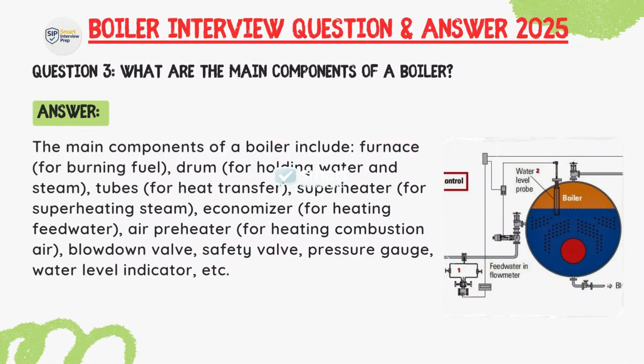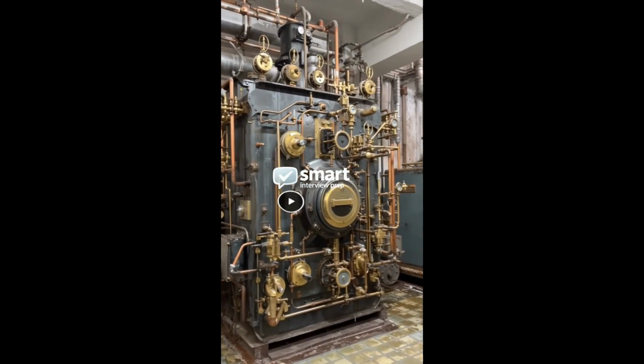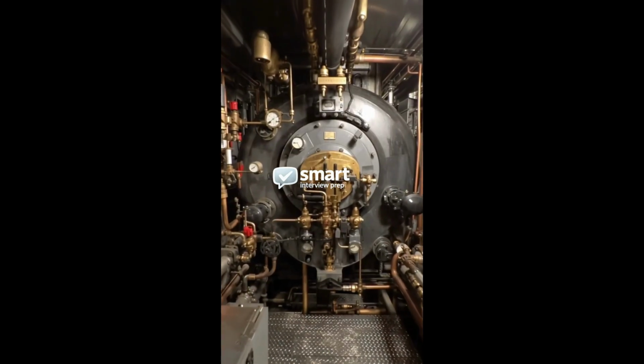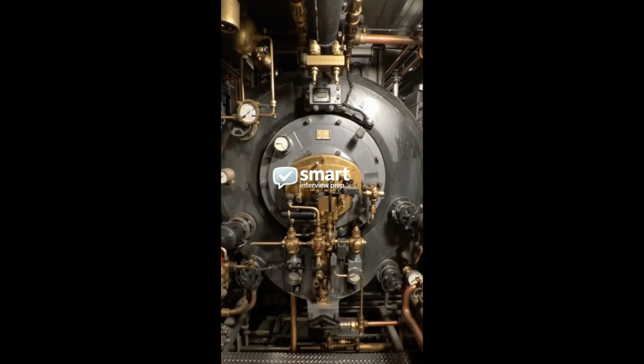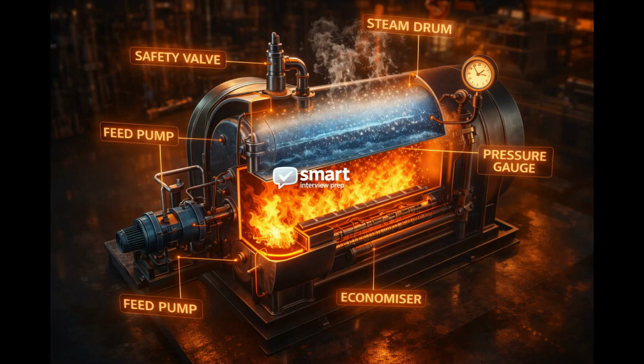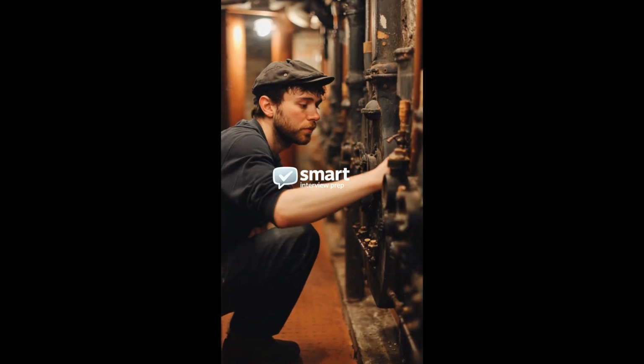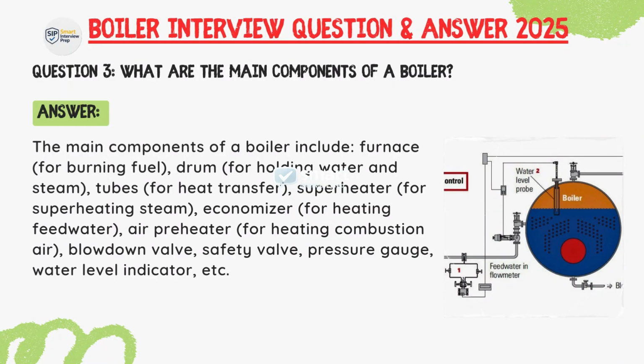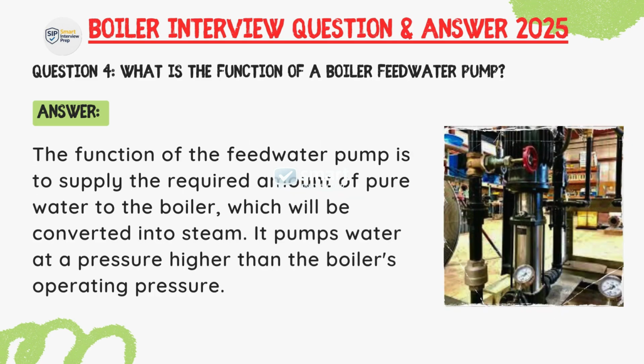Question: What are the main components of a boiler? Answer: The main components of a boiler include the furnace for burning fuel, the drum for holding water and steam, tubes for heat transfer, the superheater for superheating steam, the economizer for heating feed water, the air preheater for heating combustion air, the blowdown valve, safety valve, pressure gauge, water level indicator, etc.